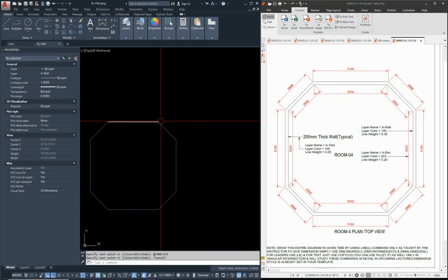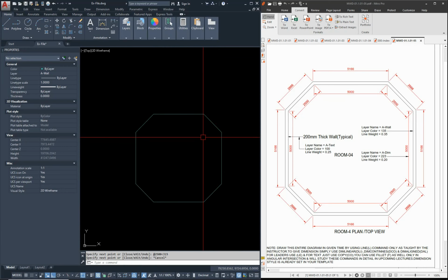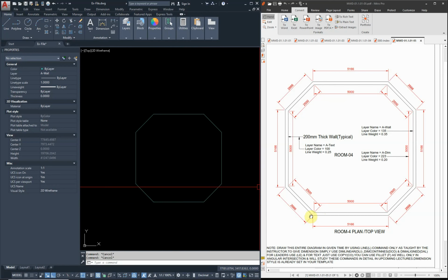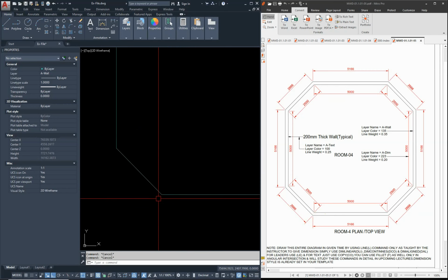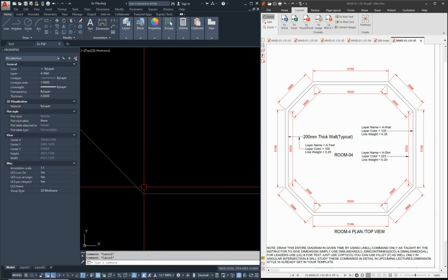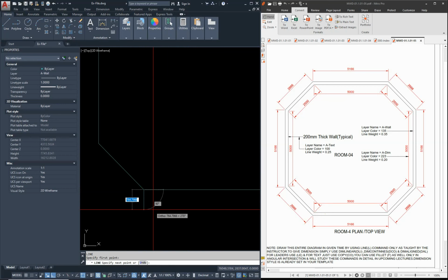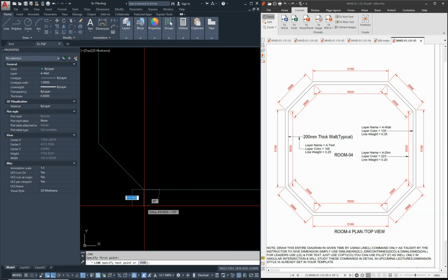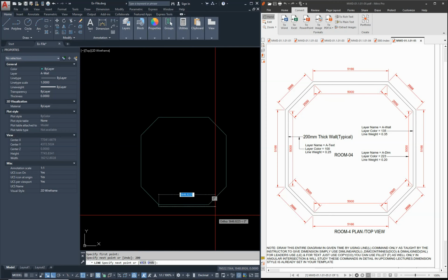Now these are just simple lines, so we have to turn these lines into walls, and to do so we will give their thickness, which is 200 mm, as I told you, standard. Now see, before the thing was different, it was a single line, but here we will not consider thickness from here. We are going to use fillet, so leave this thing. Maybe it will confuse you. Just simple line command and shift at the rate 200, simple 200, no need for at the rate as well, 200, and I just gave the command of line.